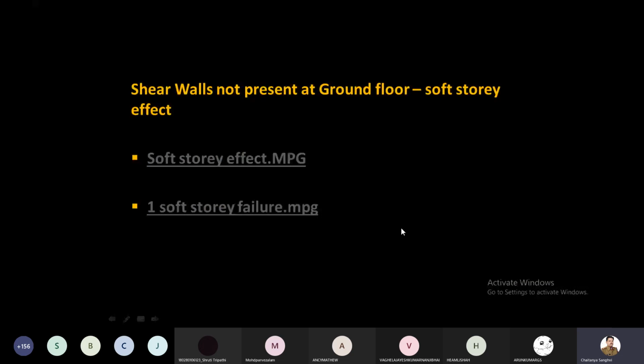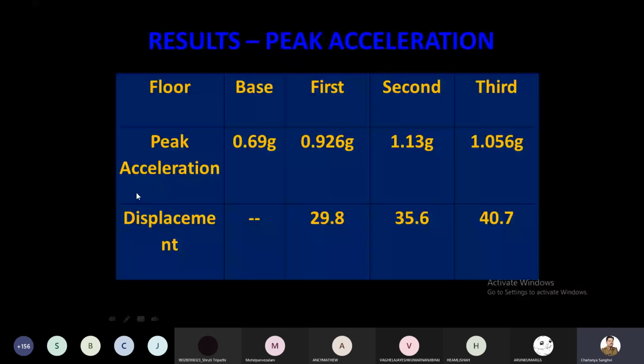And you look here, you see total displacement is 40 mm at the top. Out of this 40, 30 is observed at the first story, equal to the soft story, right? So when you interpret the result, you get the answer. Highest deformation, 75% deformation, is at the ground story, and therefore the columns are supposed to fail there, right? Then we place the asymmetric shear wall. Asymmetric shear wall means